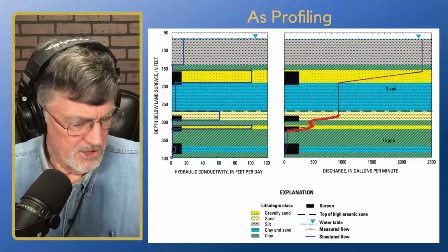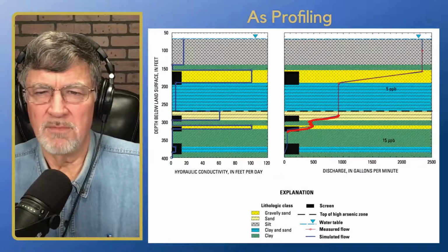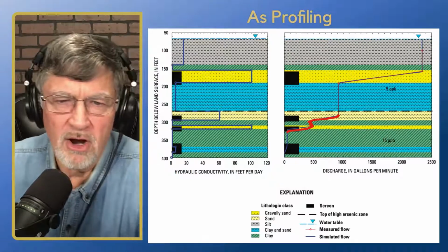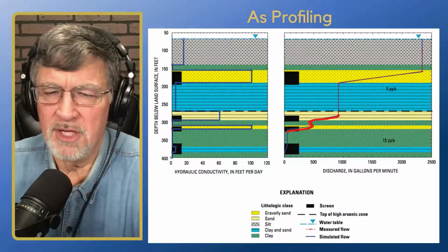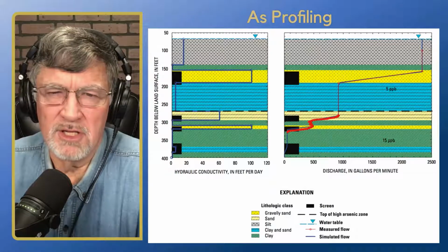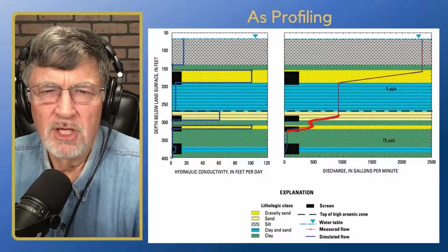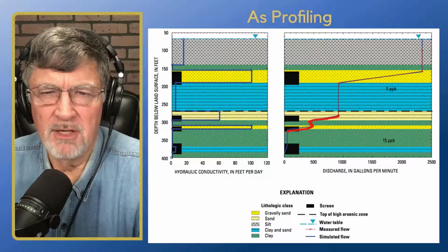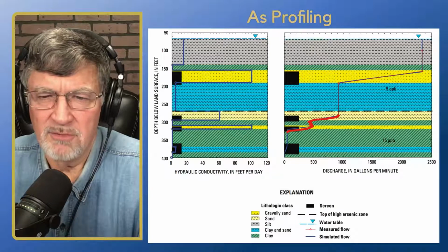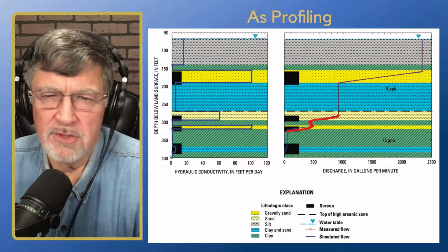So here's another example. This is using the USGS Analyze Well tool software for looking at arsenic concentrations and hydraulic conductivity. On the left-hand side, the black blocks are the hydraulic conductivity. The geology is superimposed there. We have a silt up above, a clay, a sandy zone, a gravelly sand, a clay and sand in blue, and so on and so forth down below.